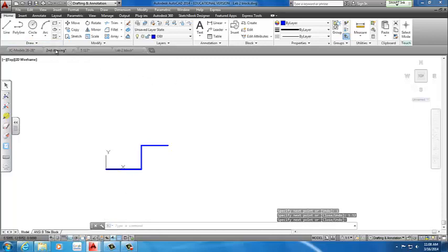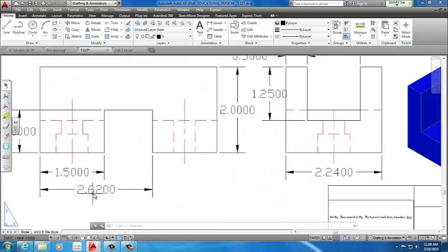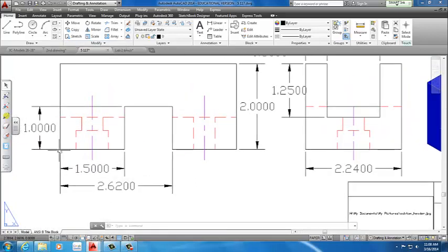Always draw on a model. That's one I recommend. If you look at the drawing, if I subtract 2.62 from 1.5, I'll have the distance here. You can see that it snaps on and even specifies that it is an endpoint. So if you don't want to do the math, you can just draw a line all the way across to this point, so you know exactly where the dimension begins.